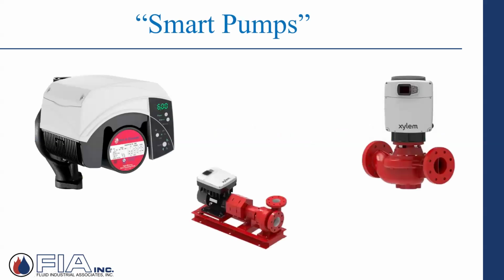So anyways, some of the technology, relatively speaking, is new. And all we're doing is it's still all variable speed pumping. It's just that you're getting into this terminology, smart pumps. So a pump, maybe a high efficiency motor, put a VFD on a wall, make it all connect, put some remote sensors. That's a VFD package, and we've been doing it for years and years. As technology continues to move forward, they're taking some of that and packaging it and putting it right on the pump. So there's intelligence right on the pump.